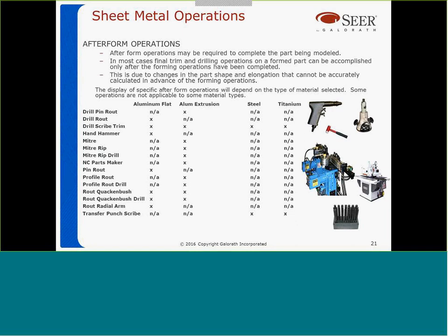Typically, after-forming operations are needed, as in the case of stretching, where you have to trim off the excess material that was held in the jaws of the stretcher. You may also have to put in holes after the forming process rather than putting them in the flat before the forming process.